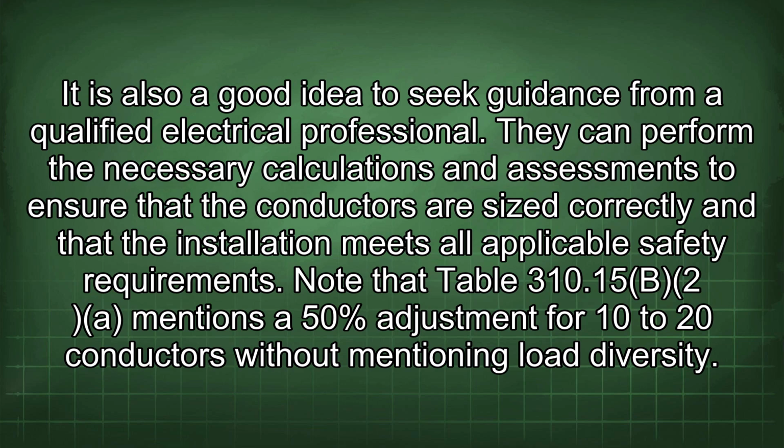Note that Table 310.15(B)(2) mentions a 50% adjustment for 10 to 20 conductors without mentioning load diversity.